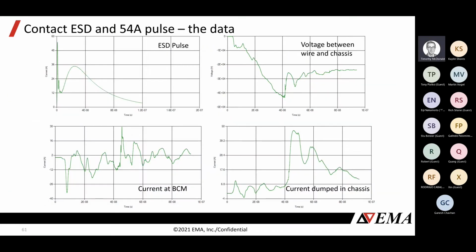So when we crank up our ESD discharge to the door handle, we observe an arc very far away from the door handle. Because we're solving full wave Maxwell's equations, we're solving the fluid flow equations and nonlinear air chemistry equations everywhere, we can find those secondary arcs. So this is just one example, but there are many, many more.